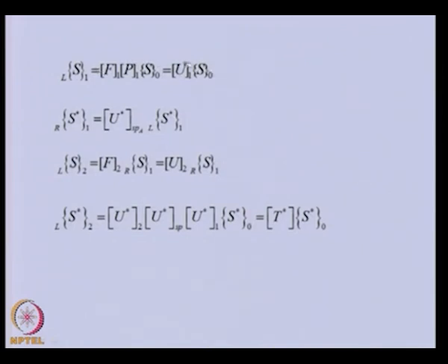So, this is the relation in which we related station 0 and 1. Previously, using support conditions, we developed the state vector relation between the left of 1 and the right of 1 of the support, and from shaft segment 2, we earlier related the right of 1 state vector to the left of 2 state vector.